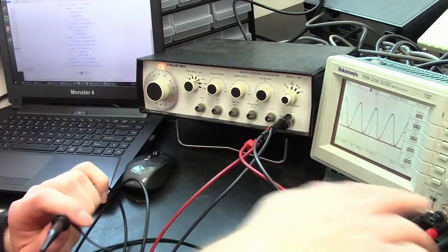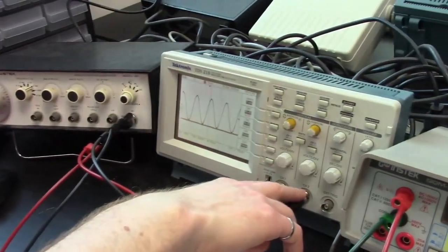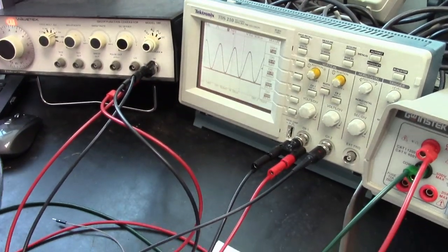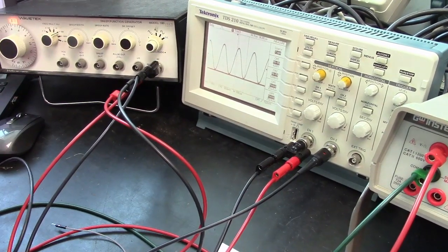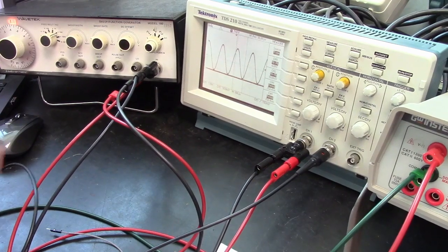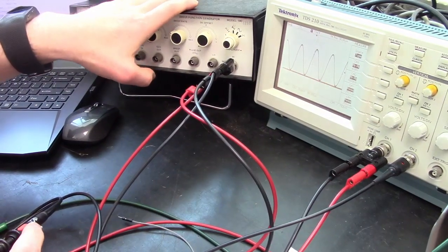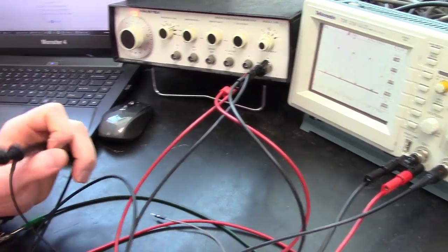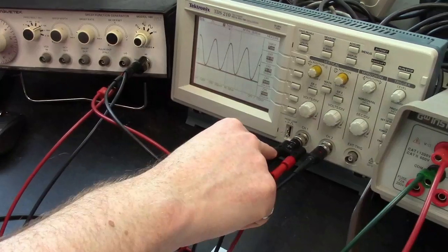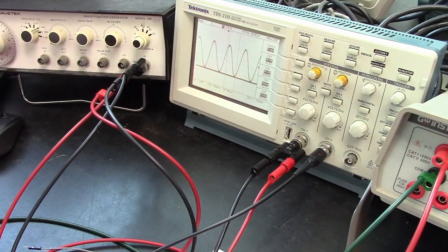The other thing is the outside terminals, so the ground pins of the scope, are connected to each other, and in fact connected to instrument ground through a DC stopping capacitor and a 50 ohm resistor. So that means that whenever you have this hooked up to something that's measuring AC output by the function generator, you have to set it up so that your ground of this is connected to the ground of the function generator.